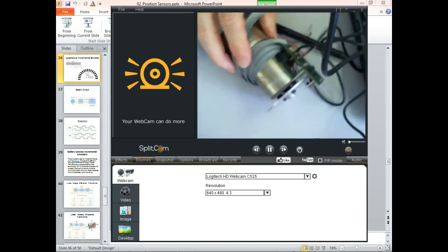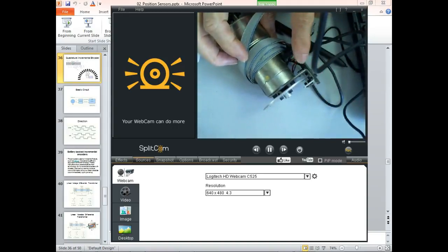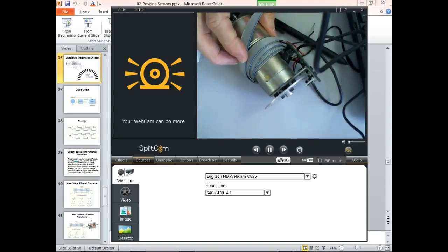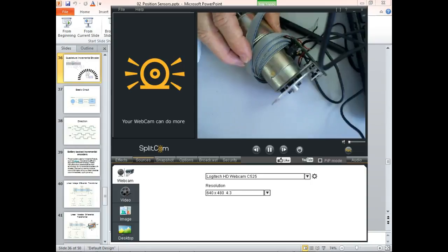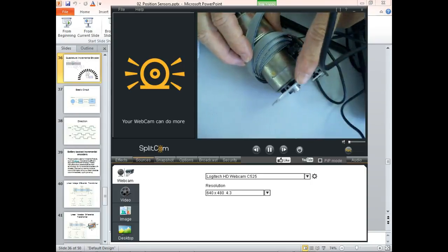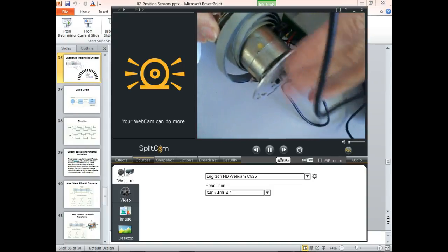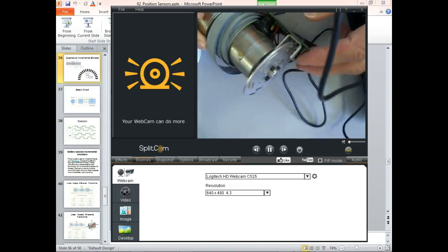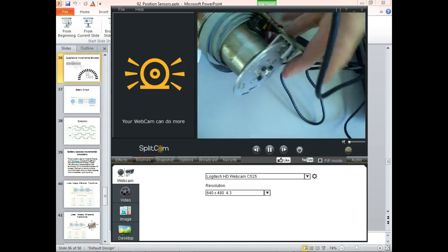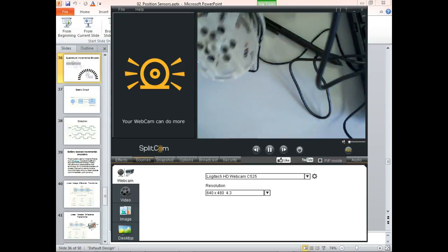Because it's hard to see the actual sensors on the encoder. So what we're going to find out is, a lot of our sensors, we have to use other sensors to cause that sensor to work, right? You understand? So here, this is the sensing element right there. But this means nothing unless I can convert it over to a series of pulses. So here we're using a light sensor, and we're using this as the actual sensing element. Does that make sense? This would be an incremental encoder.